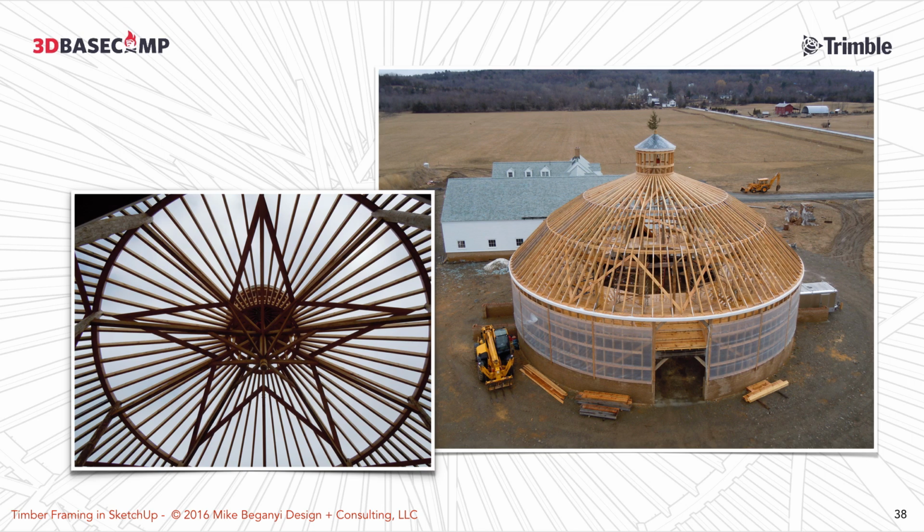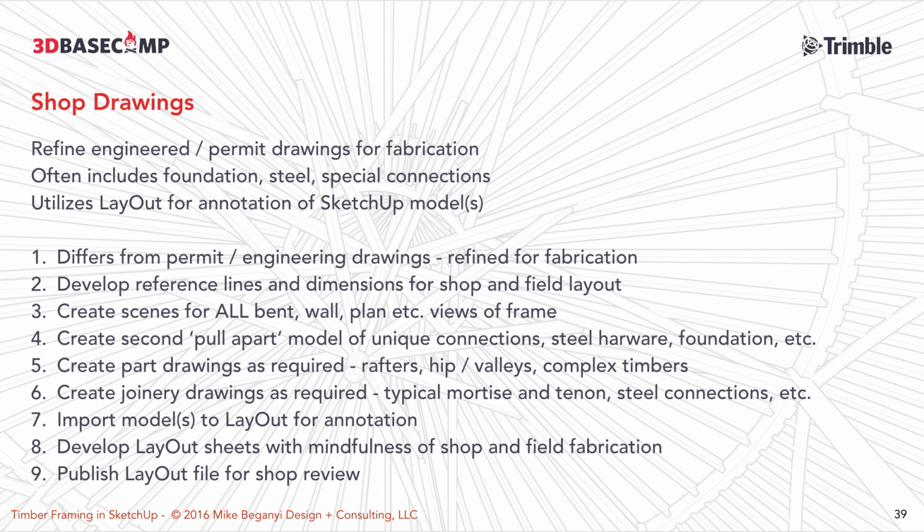standing. So shop drawings typically take that refined engineered permit set and will include the foundation, steel connections. Again, I utilize layout. This differs though from permit drawings because there's a lot more information that you need for the guys either in the shop or in the field. The building department is not going to come in and check that your rafters are the exact right length to the bird's mouth cut. They're not going to check the center lines of the posts so that the guy can actually cut the pieces that fit in between.